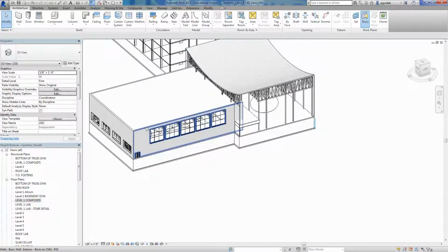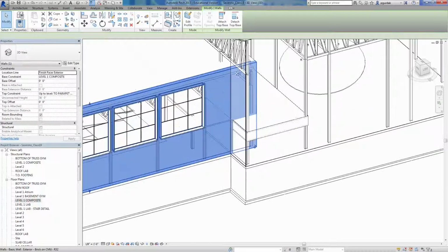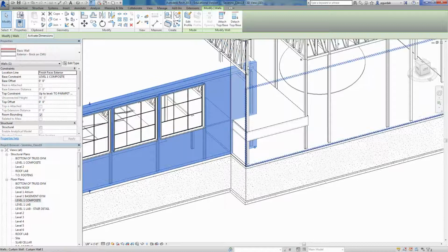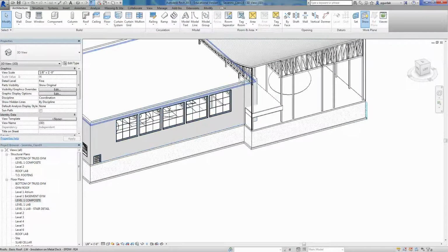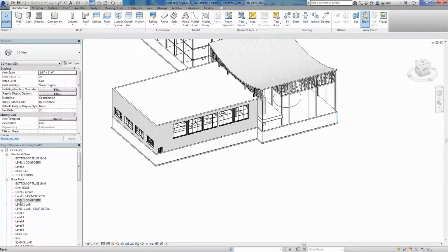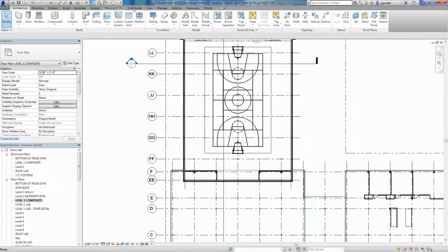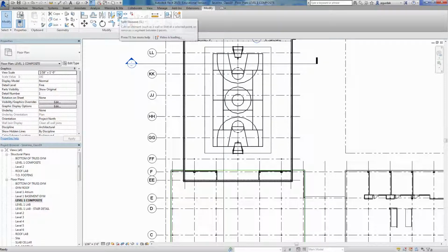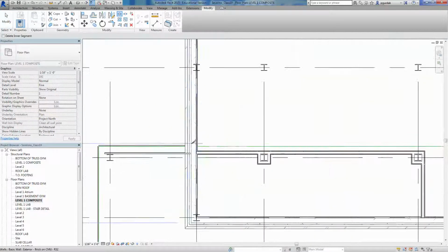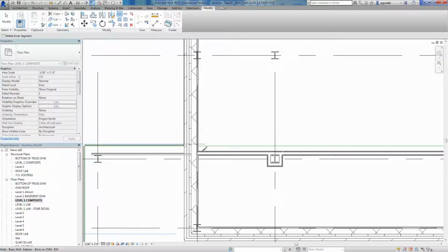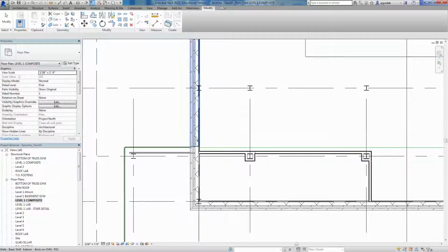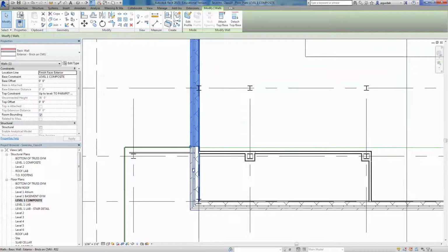If we select the wall, we have a door here, a wall that goes through the building and into the atrium. So we want to first actually split this wall. For that, I'm going to use the level 1 and the split command, which is right here, split. And I'm going to make sure that I go outside of the green line and split that wall. If I escape now, I select it. This is one wall, this is another one.